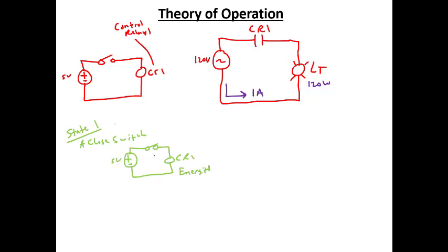If we had a 5-volt supply, that means that we would have 5 volts across the coil and the electromagnet would turn on. In this scenario, we would have 0 volts across the switch, and Kirchhoff's voltage law would still apply: 5 volts equals 0 plus 5. Now, for the contact circuit, we have 2 circuits, the coil circuit and the contact circuit.